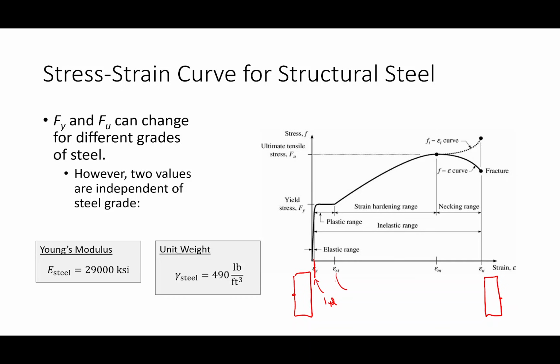This part right here, where we start to begin strain hardening, the structure starts to realign and it can start taking load again. That's about the 10 yard line, okay? And then we can keep on going. When you're applying the load, the ultimate tensile stress, that's when the specimen starts to do the necking, when the center starts to suck in a little bit, and then it goes. All right? Does that make sense?